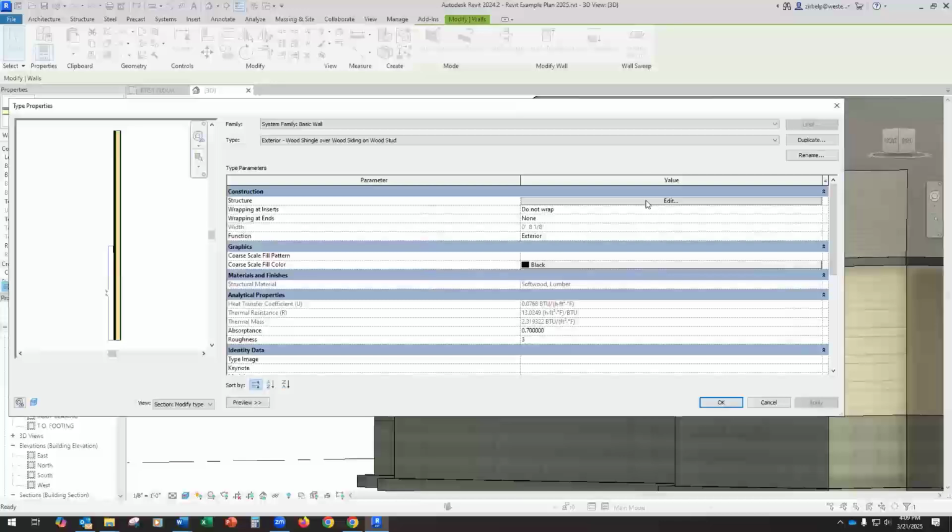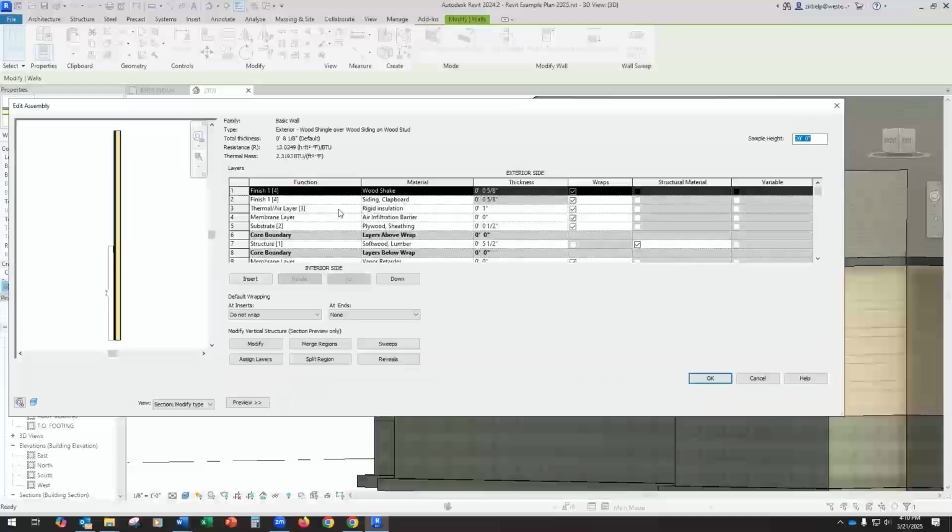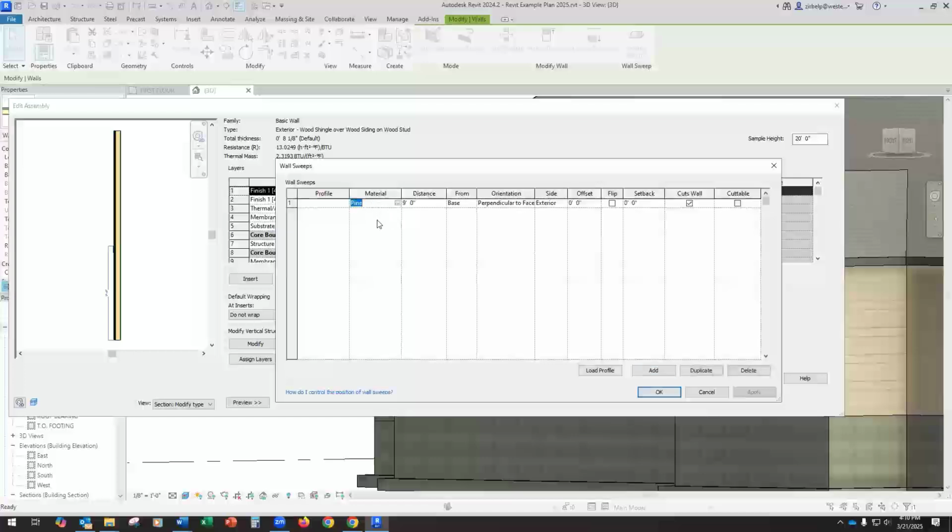So this is a little bit of an unusual sweep because it comes from Revit, and however it's programmed, it comes in without a profile when you look at that sweep. So there's really no way of adjusting. You can adjust how high it is up or down, and you can adjust the material, but you can't adjust the actual size of it. So if you go to this drop down and you hit default, and you hit apply, you can see the default is just the standard square, which we don't want. So I'm going to hit cancel and get out of there.